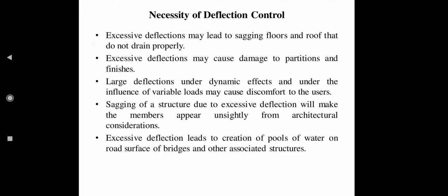So if the deflection is more, the floor will be under sagging condition. If the floors are under sagging condition, then the water may not be drained properly. When the water is not drained properly, the stagnant water may cause damage to the member. Excessive deflection may also cause damage to partitions and finishes. So if the deflection is more, it may cause damage to the partition walls and to finishes like false